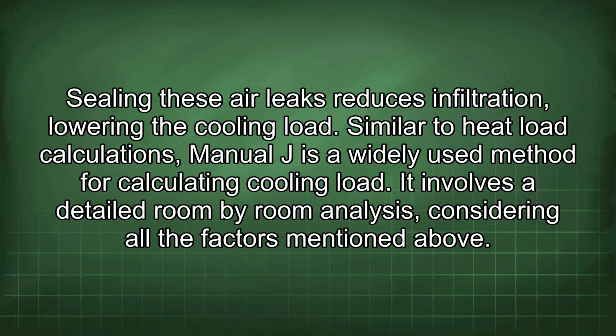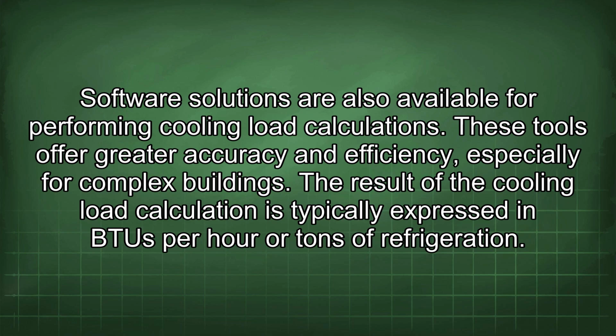Similar to heat load calculations, Manual J is a widely used method for calculating cooling load. It involves a detailed room-by-room analysis, considering all the factors mentioned above. Software solutions are also available for performing cooling load calculations. These tools offer greater accuracy and efficiency, especially for complex buildings.